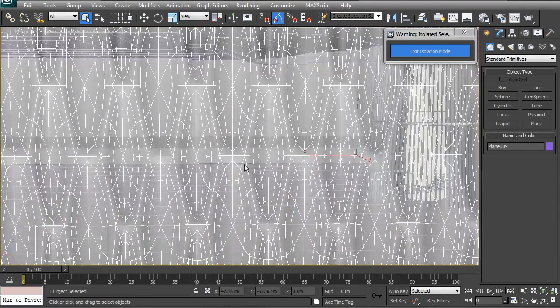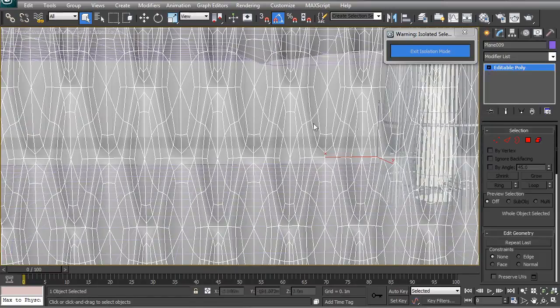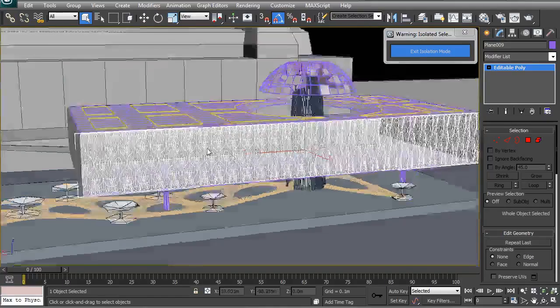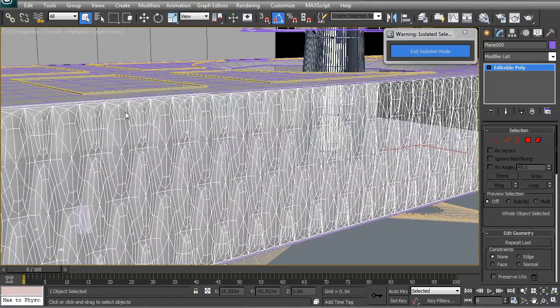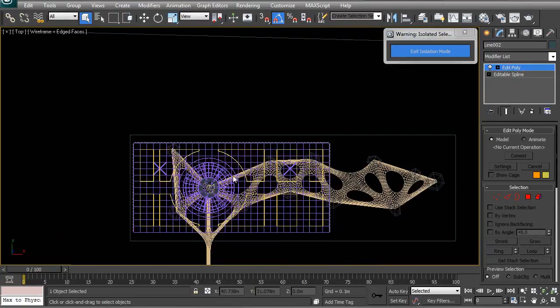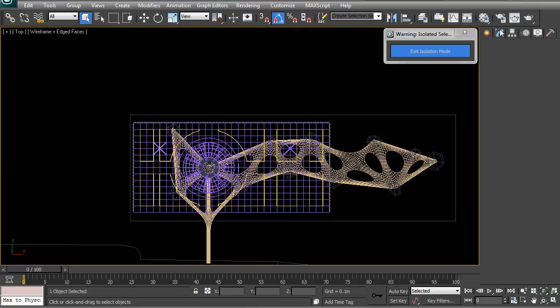If we did a flatshot or a flatten command or anything of that sort, we would actually end up getting all of this tessellation, and even if we removed the tessellation, if we went back into the previous files as we were modeling the building, we would still not really have the actual shape represented correctly. So what I'm going to show you in this lesson is just how you can use the section object that we created earlier when we were generating the section to create an interesting shape for that.